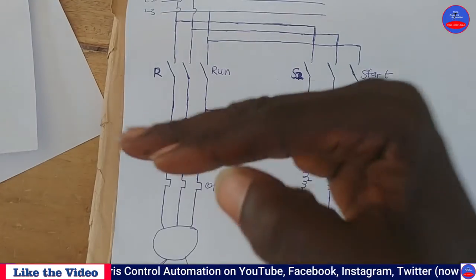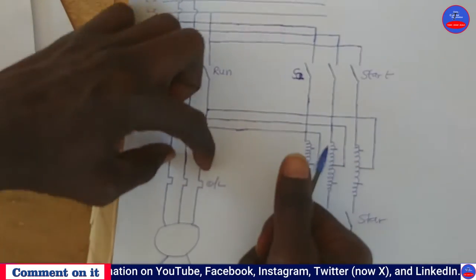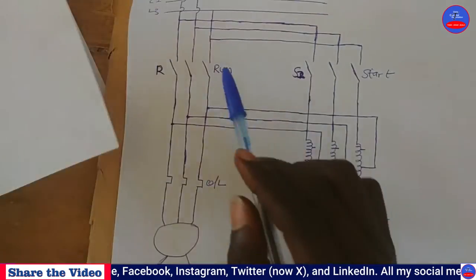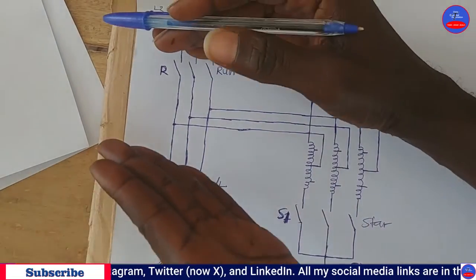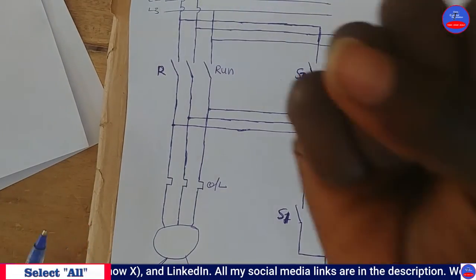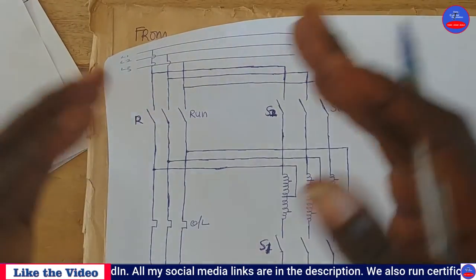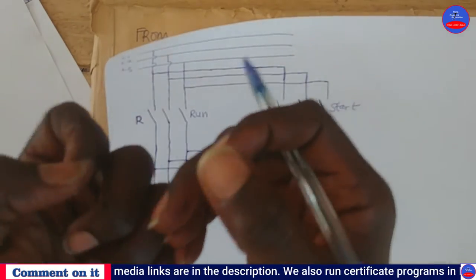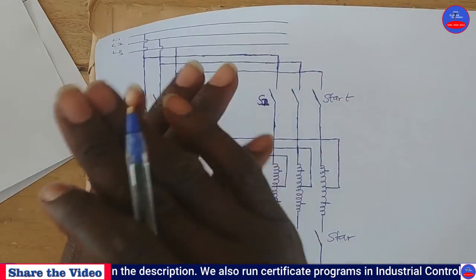So in that case, the motor is going to act as a generator to generate some back voltage here. So when the run contactor energizes and also applies the 3-phase voltage onto the motor, the two voltages are going to meet. In that case, it is going to cause a high surge current, high transient current, and it will also trip breakers, blow fuses, and cause voltage dips or voltage drops on supply systems.